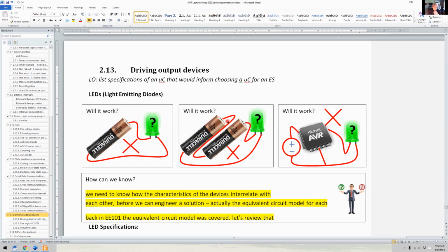Well, you might think, let's just double that voltage because we've got 2 cells. We'll put them in series. That gives us 3 volts. Well, actually, it gives us anything from about 1.8 volts if the cells are pretty flat, through to maybe 3.4 volts if we've got 2 cells connected in series. And that's probably too much for our LED. You try it at home. The LED might work. It might change color a bit and then stop working.